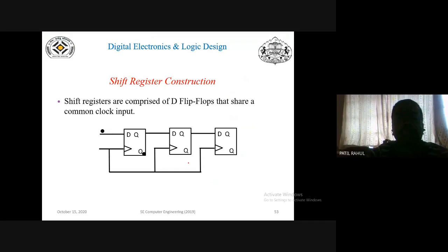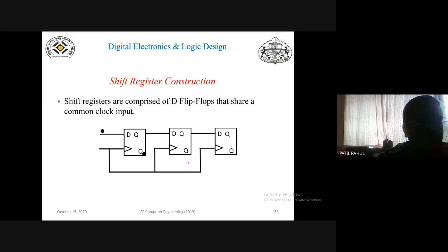This is the shift register construction. One point is to be noted in your mind: always use the D flip-flop for storing the data, and always we apply the same clock pulse to each flip-flop. This is known as the synchronous clock pulse.